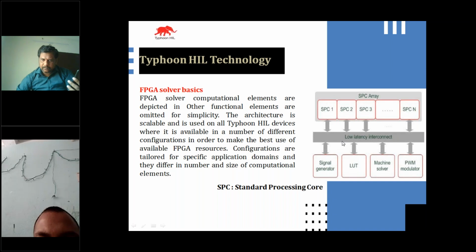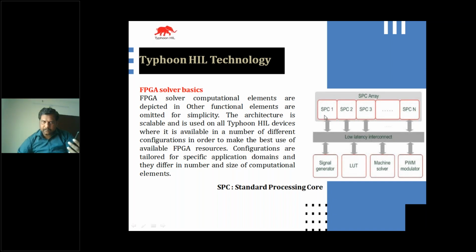So what does the FPGA solver include? You can see this is the SPC array. SPC means standard processing cores. A standard processing core is a basic building block of the circuit solver, and it is in charge of simulating electrical circuits consisting of linear passive elements, both constant and time varying, converter blocks consisting of ideal switches, then contactors based on ideal and non-ideal switches.